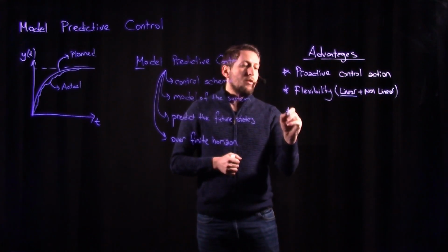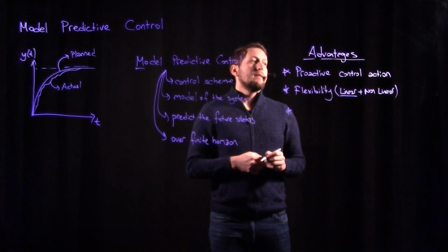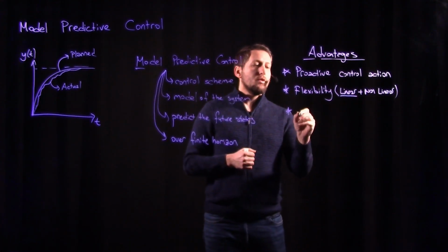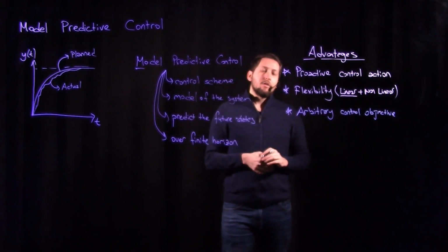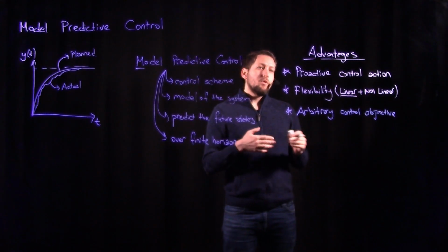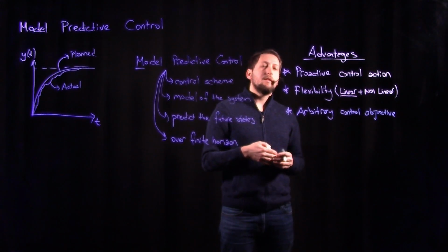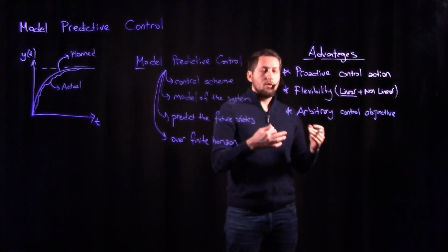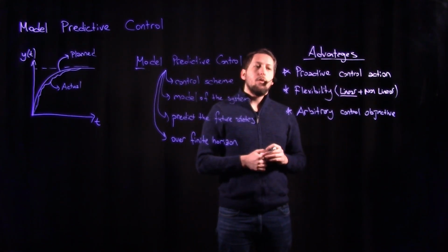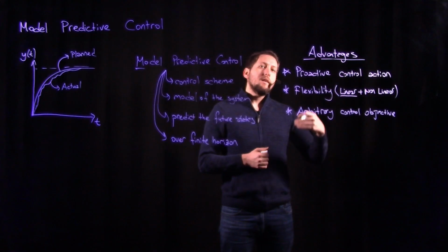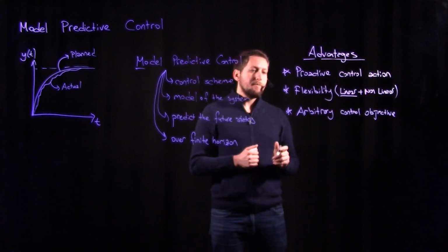And of course, model predictive control will also give you flexibility in terms of control objective. This means that in the traditional control approaches, set point tracking is mostly considered, but in addition to this, you can also define a control objective or reference curve that fits your scope better, so that you can enter this into your problem formulation and hopefully get better results.